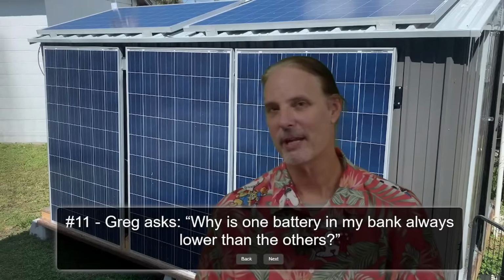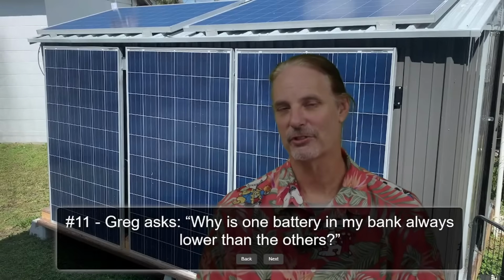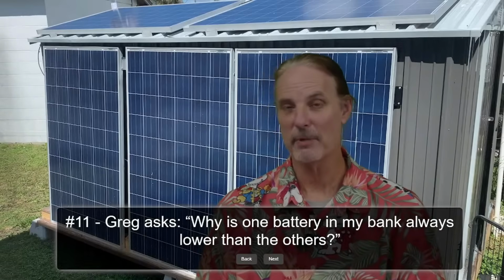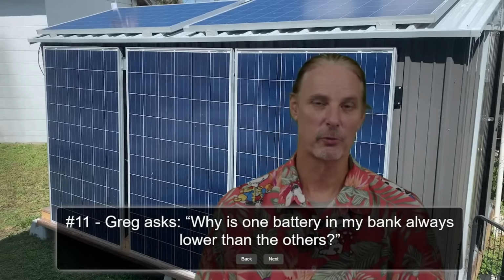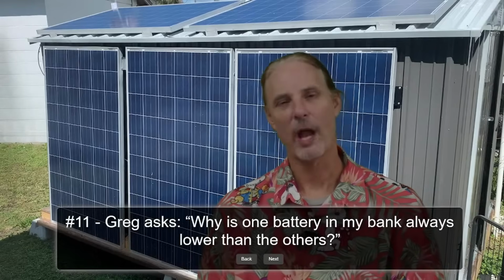So, considering I use the state of charge out of my Victron, I haven't actually gone to any efforts to see what it would take to recalibrate the EG4 batteries. In the JK BMS, it's very easy. You go in, you measure the voltage, you set the voltage to what you've got it measured at, you measure the amperage and you set that, and everything's right as rain.